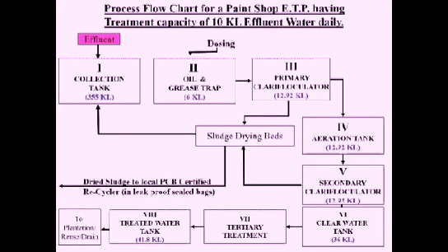Through aeration we can speed up the biodegradable activity, and secondarily we can put in catalysts like yeast and coal or any other substance which stimulates the bacteria to have a faster life cycle, and the waste becomes neutralized. From the aeration tank, the comparatively clearer water is pushed to the secondary clarificator, which again in this case is 13 KL capacity.